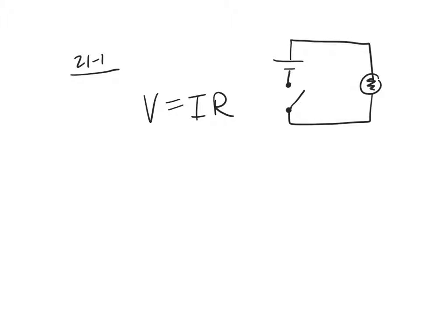Exact same thing. What happens is this: if there's no element, suddenly there's going to be a super high current, because no element involved means no resistance. No resistance means the current's going to spike. When the circuit breaker senses a high current, it trips or opens up a switch, which stops the current from flowing so the wire doesn't overheat and cause an electrical fire.